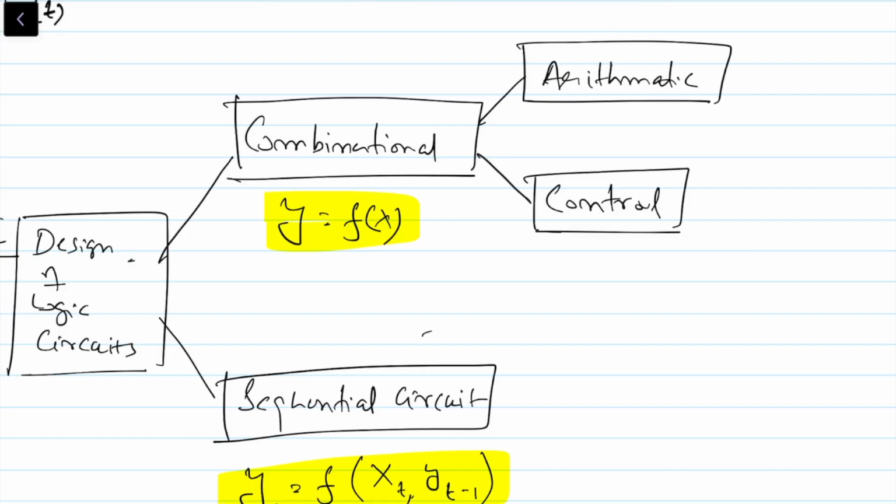Another reason for studying sequential circuits is to get the notion of building a circuit which behaves like a memory cell. We will see the trick to trap voltage, current, or charge inside a circuit to retain information. The elementary circuit that will behave like a memory cell is called a flip-flop.